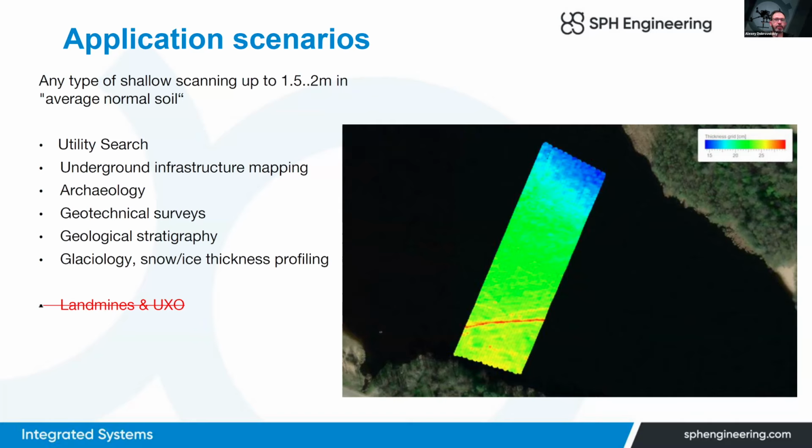GPRs, and actually not only airborne GPRs, but also terrestrial GPRs on a cart, will have so high false positive rate that they become absolutely useless. For every real target, we had dozens of false anomalies from natural objects like cobbles, stones, just pieces of the soil with different permittivity.